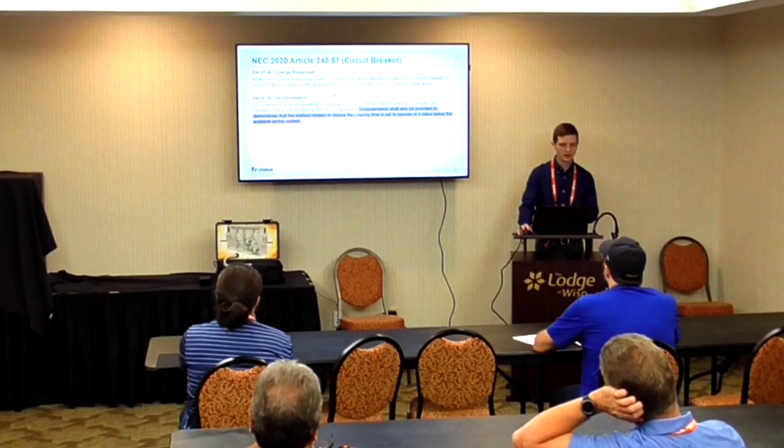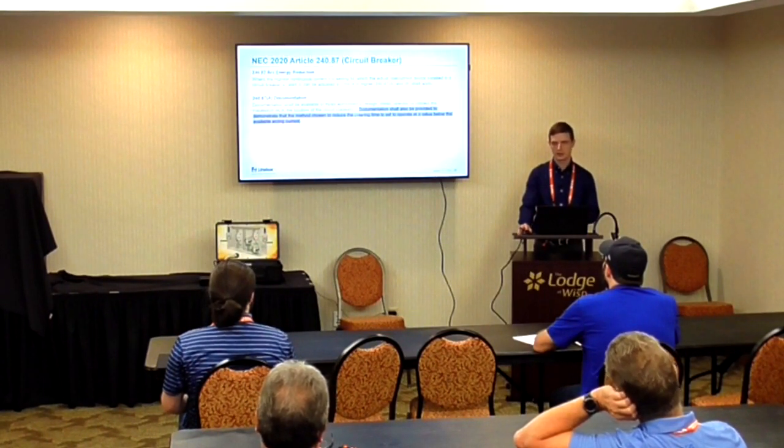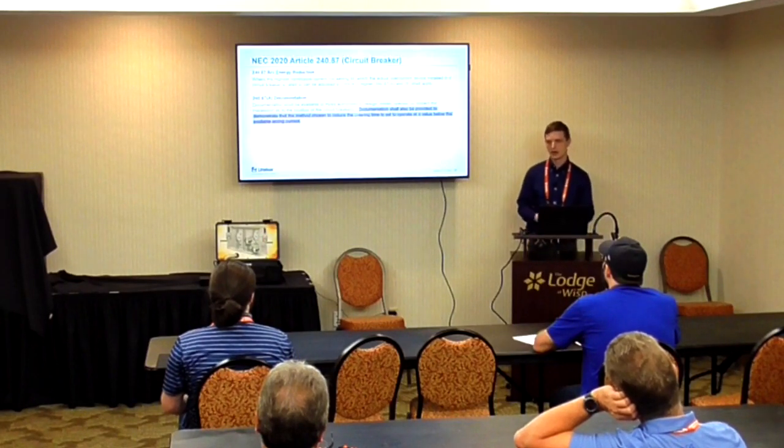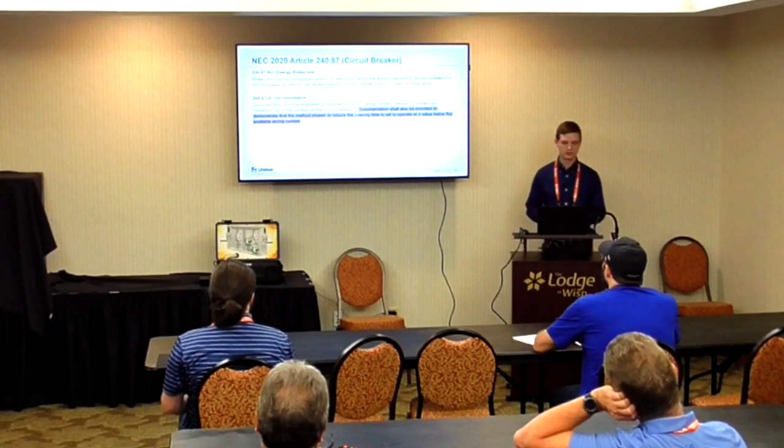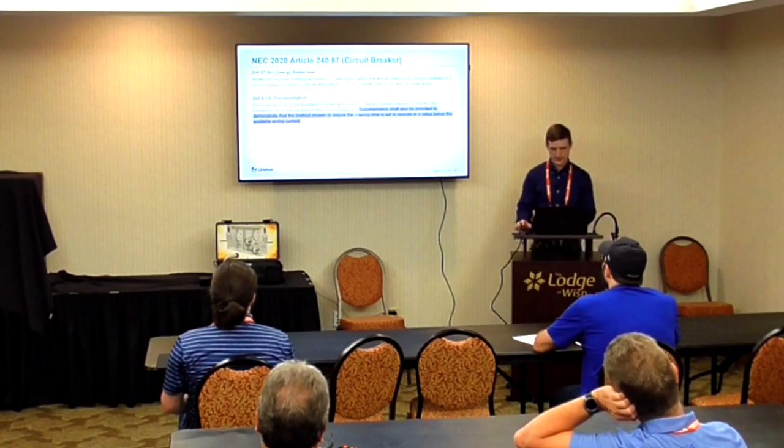Something that's important to note here is that it says it can be adjusted to 1200 amps or higher. So if you've got something that's 800 to 1200 and you've got it set to 800, this still applies to you. Because if somebody comes along later on and they add something else to the system, they say, okay, well now we need to increase it to 1200. That needs to be already taken into account during the design phase. So essentially what that means